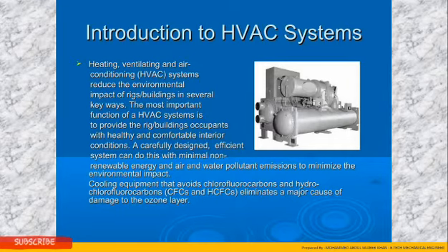Now, as we are all aware, CFCs and HFCs are terminology related to the types of refrigerants used in an HVAC system. Basically, R22, the refrigerant which is the major cause of ozone depletion, is now completely phased out. So just to give you a brief flashback of the understanding of the refrigeration system, the commonly used refrigerants now are R134A, R410A and R407C.